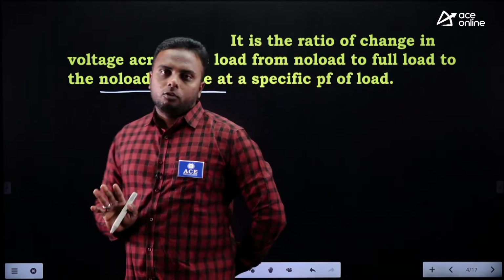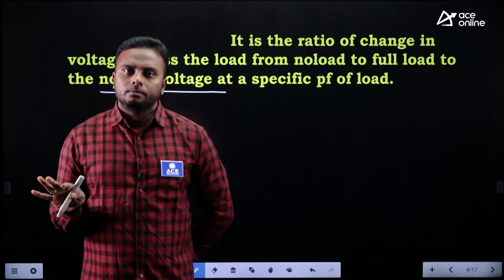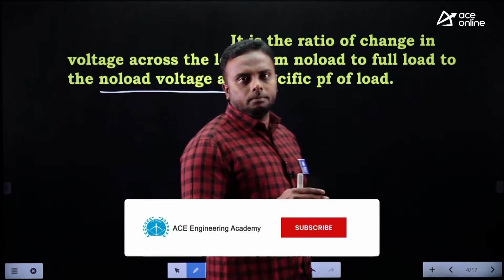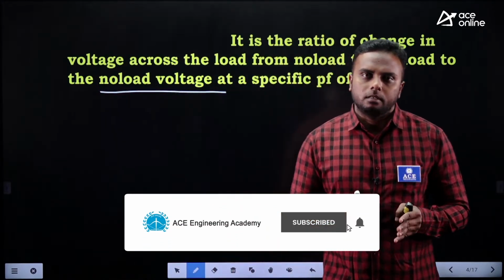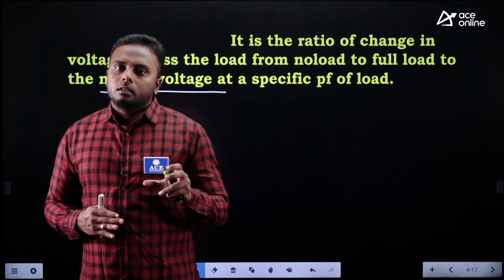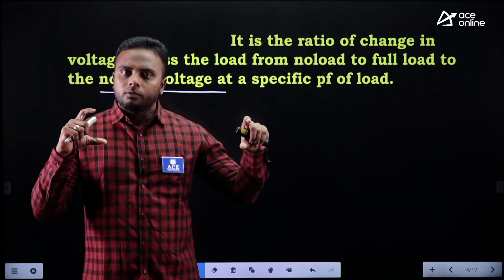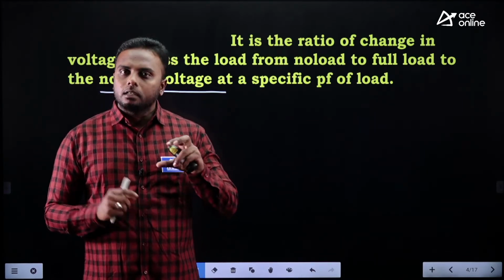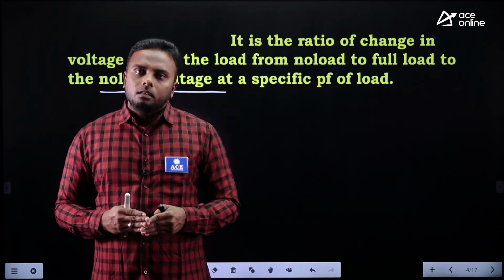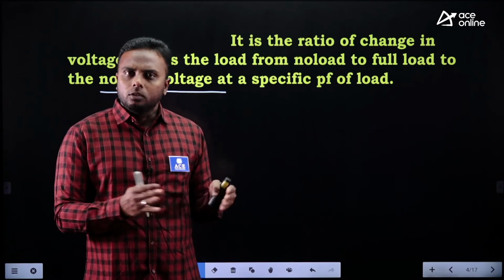But practically, what loads are we mostly connecting? Lagging loads with power factor in the range of 0.7, 0.8, 0.9. Mostly we operate transformers like this. So definitely for lagging power factor, the secondary terminal voltage is less than the induced EMF of the secondary. If the EMF is 200 volts, we definitely get a little less, sometimes 197, 196, 195 or 192, in that range.